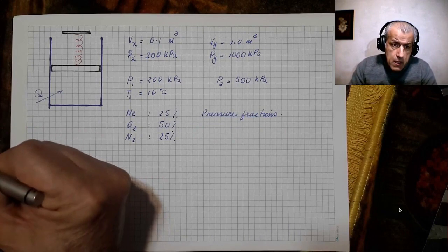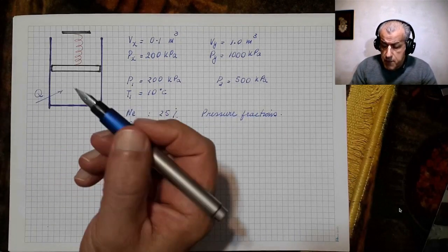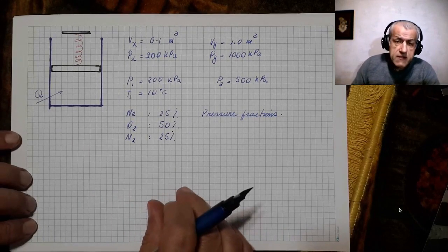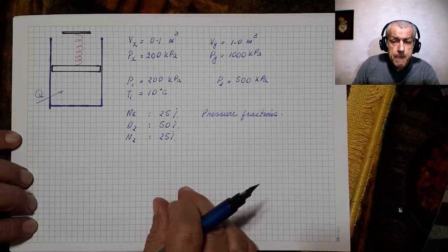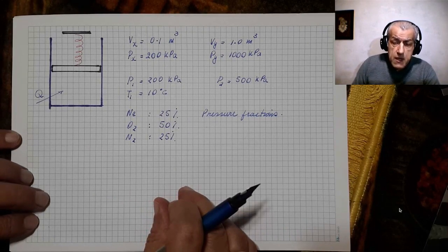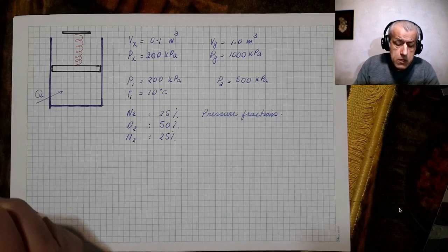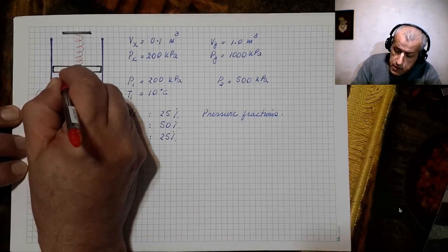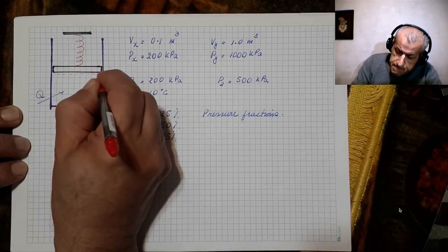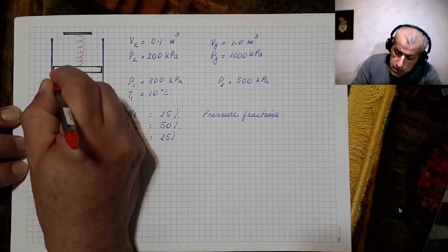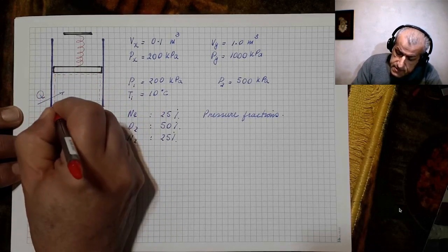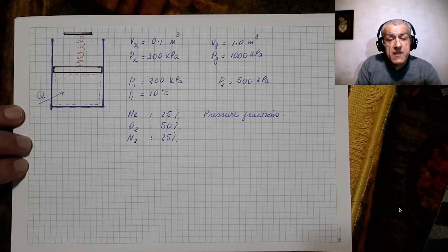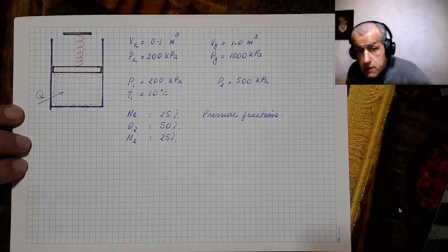Now, the solution to such a problem is very similar to whatever that we always did. That means that we shall write our equations, decide on our control volume, simplify our equations for this control volume, find properties, draw process and properties on a diagram, and then get everything together towards a final solution.